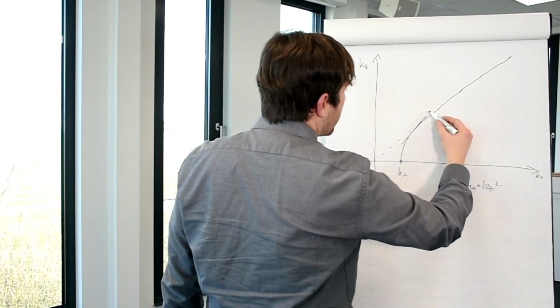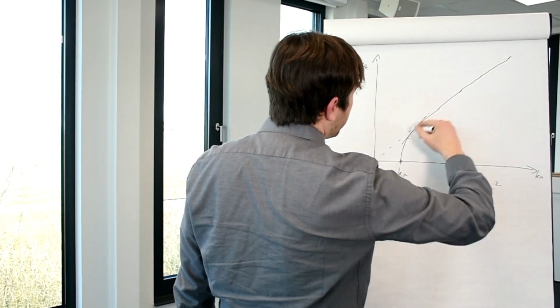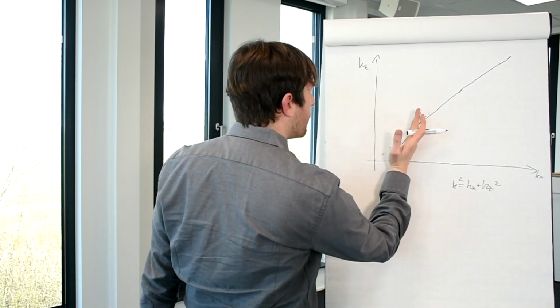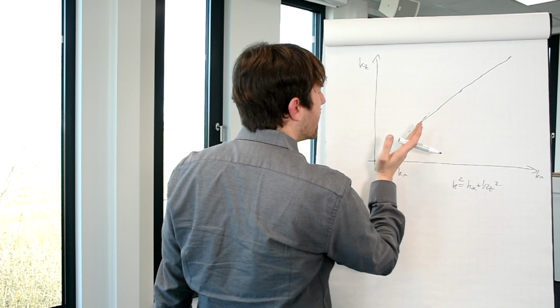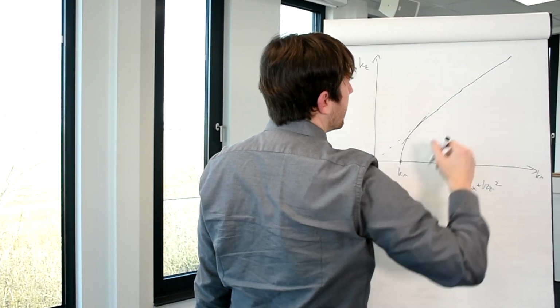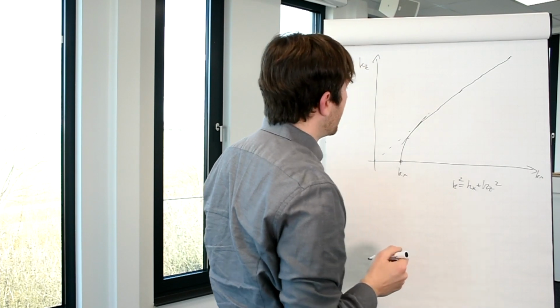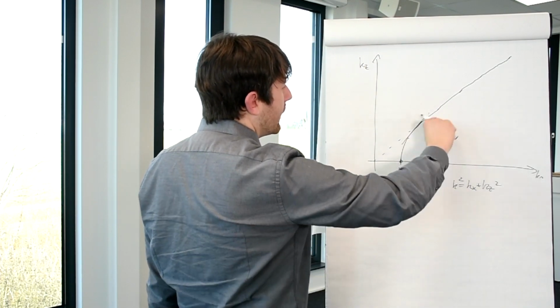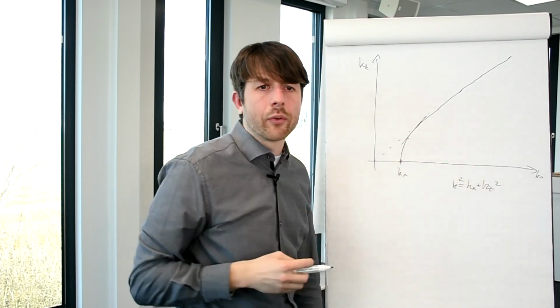But here, you try to get a linear spacing for kz, and this interpolation is a Stolt interpolation. So it's more and more critical the closer you get to the object. And kz over the frequency is then less and less nonlinear. So that basically compensates for nonlinearity errors you have in close and near field. That's the role of Stolt interpolation.